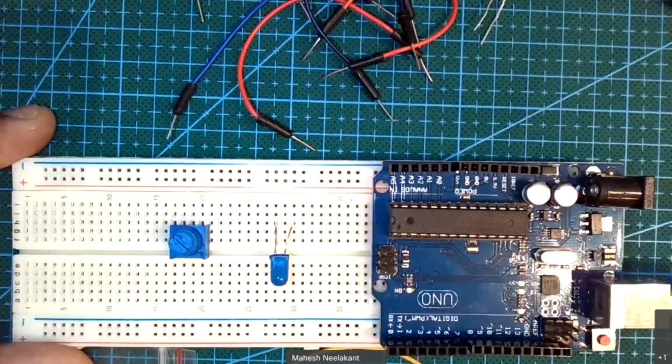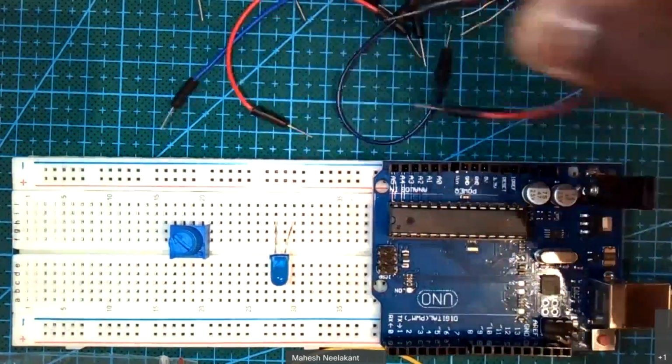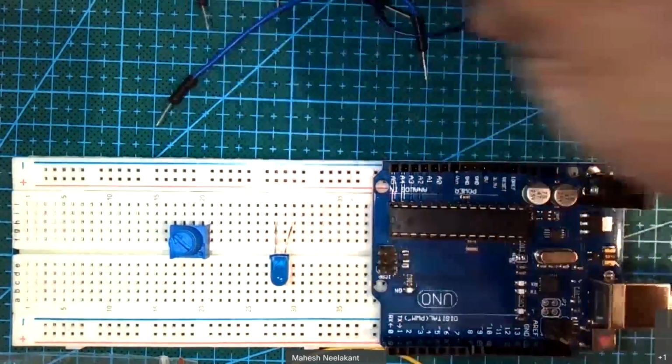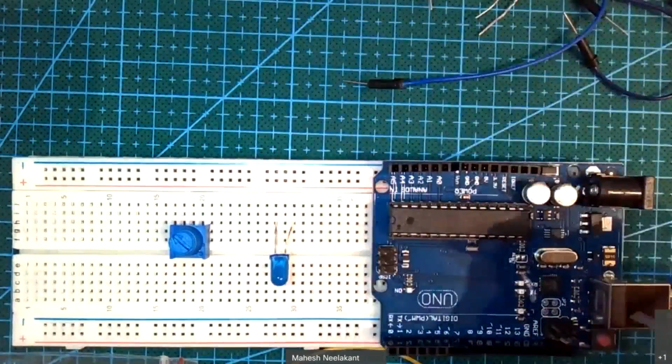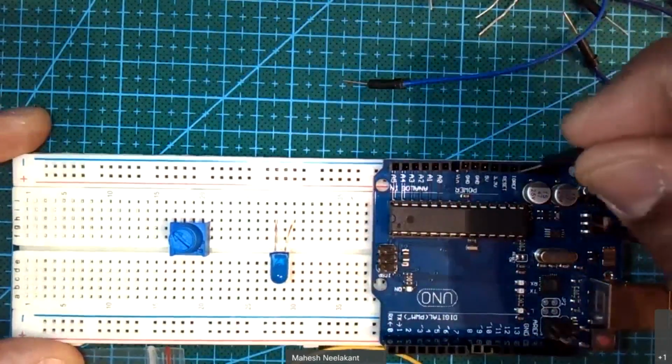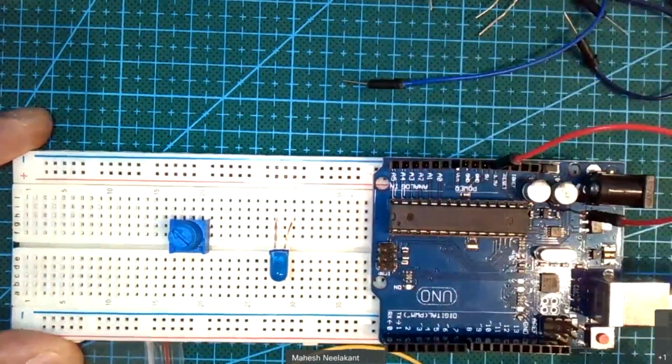And I'm going to bring that over here. Okay, so hopefully all of you can see the board. So the first thing that I'm going to do is actually connect up using the red and black jumper wires right here. Now, usually you use red to represent positive or voltage. So in this case, I'm going to connect that up to 5 volts.